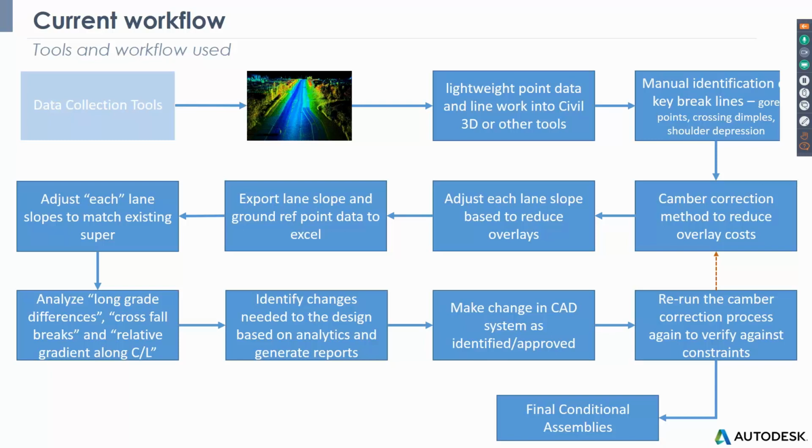So that makes it bumpy. Sometimes it is not safe, sometimes it is not pleasurable ride-wise. So they keep adjusting lane to lane, and then they do a lot of vertical adjustments for how much minimum leveling I want to do, or maybe this area I want to do milling, so what's the minimum milling depth, and where is this minimum milling depth, and do I have rutting, or do I have potholes or bump-ups? All that kind of thing they do, both graphically as well as in a tabular manner,